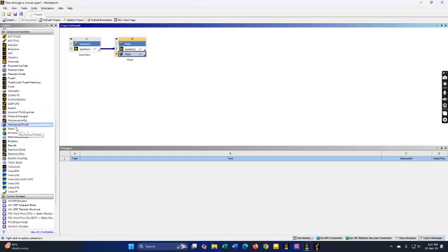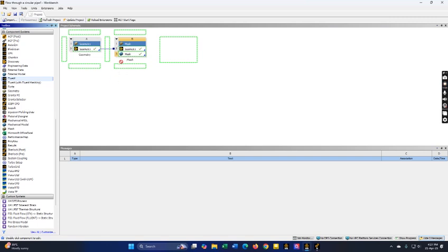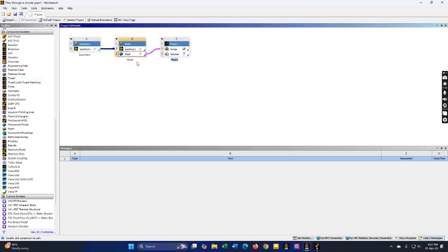Now we will be solving in Fluent, so locate Fluent and drag it here, and you see the moment I drag Fluent in this box, you are seeing an update option. This is important because the mesh has to create an .msh file, or simply a mesh file, for Fluent to solve. Before putting Fluent here, mesh did not create any file for Fluent, so I had to manually create it. So just right click on the mesh and update, and you should see a tick mark here, and the tick mark is okay, and go to setup now.